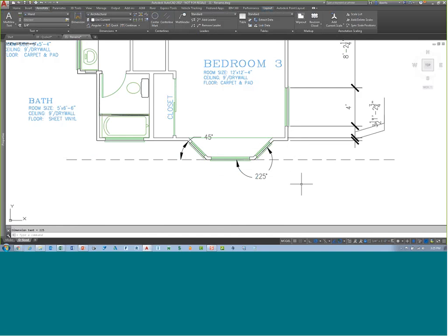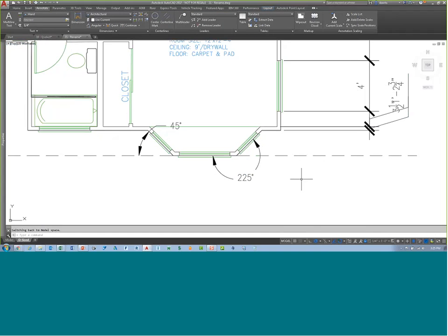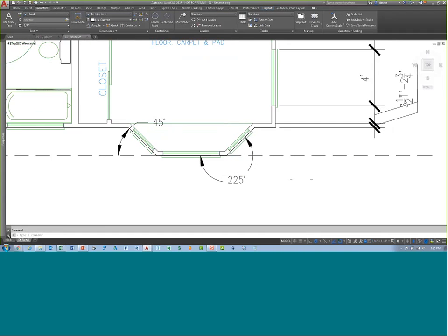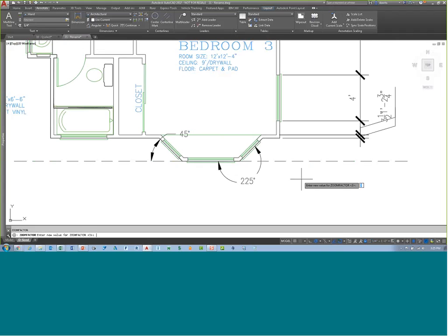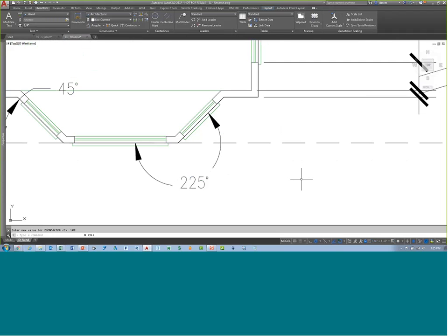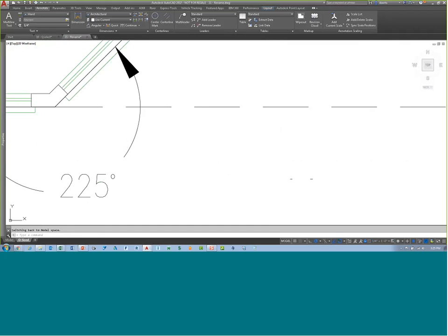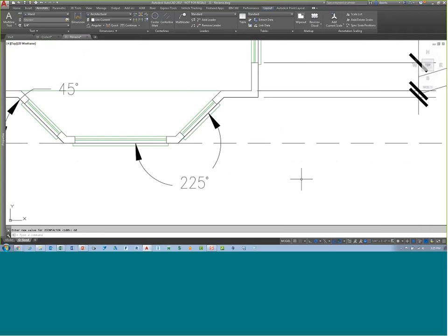Okay. Mouse wheel zoom speed. There is a system variable called zoom factor. The default is 60. If I switch it to 3, which is the lowest setting, my zooming with my mouse wheel is really, really slow, and really small and granular like this. But if I set the zoom factor to its highest setting, 100, and I scroll the wheel, it jumps drastically. Okay, so I'm going to switch it back to 60, a little bit more reasonable. Think of this, for those who are in gaming, I have a Razer gaming mouse, and I can set the DPI resolution on the fly from as low as 1800 to as high as 16,000. And so that's what this is doing to a degree.